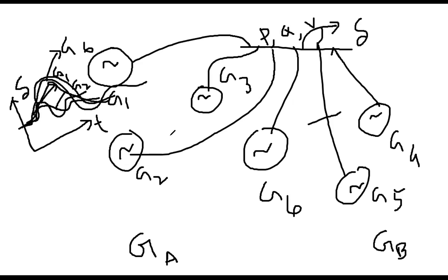So you will notice that the generators which are swinging with power angles very close, typically within 5 degrees, like one is going in that way and the other is also pretty much similar, the distance from here to here only 5 degrees angular distance, you can treat as a coherent group.